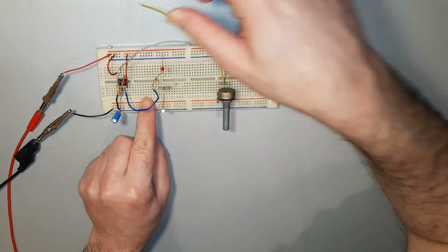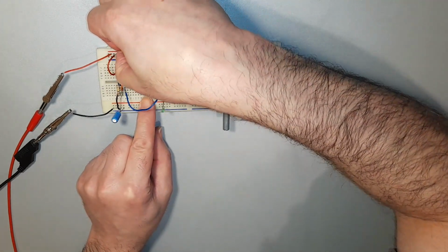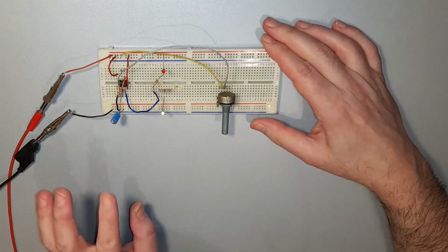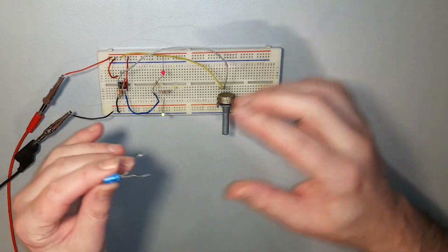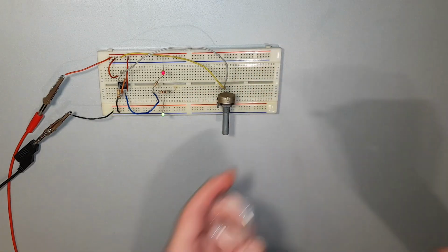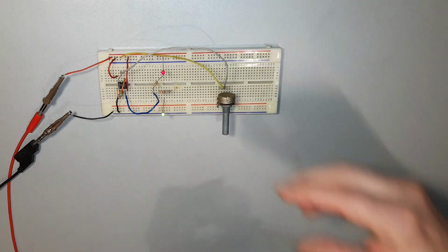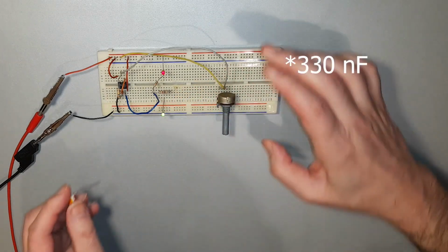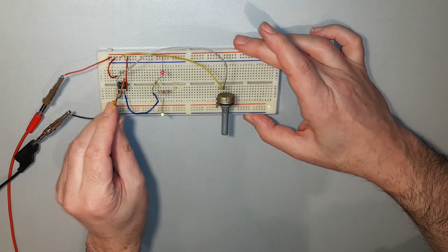That goes to pin 7. That goes to positive. And now we're done with just our little check. So we're going to now swap this capacitor out, which was 10 microfarads. Is that 10 microfarads? Yeah, that's 10 microfarads, so that's coming out. We're going to put back in this 470 nanofarads right here, here and here.